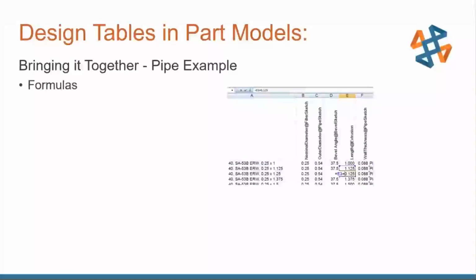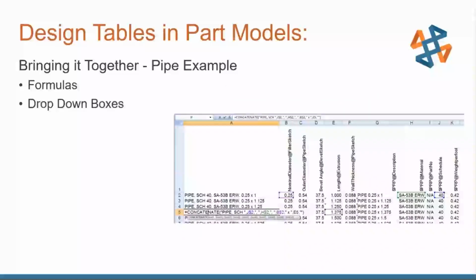make you sit here while I make 810,000 configurations. I'll build, I think, 20 of them. To help facilitate this in the Excel spreadsheet, I leverage some formulas to auto increment that 1/8 inch value. Some drop-down boxes help us make sure that we have the appropriate schedules, and we can link everything together. But what's really helpful is the concatenate formula.